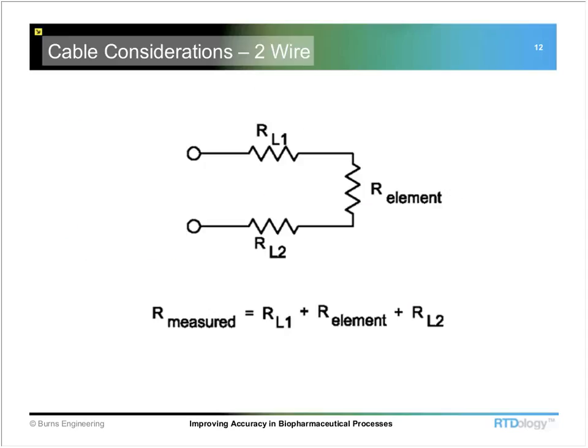So, Bill, just one more comment on that 4-wire. As far as recommending that, you do have to have a control system or transmitter that handles a 4-wire system. Otherwise, you don't really get the benefit. A lot of times, we will see people that go ahead and buy a 4-wire, and then they only connect it up to 3 terminals. You don't get the benefit if you're not able to connect it up correctly with the control system or the transmitter that you have. Right.